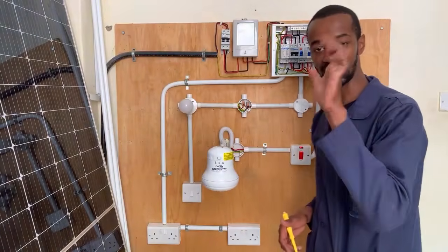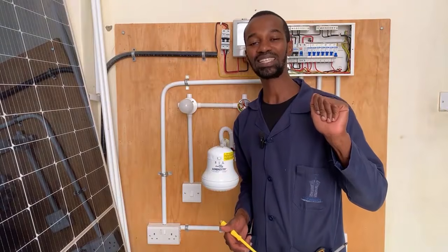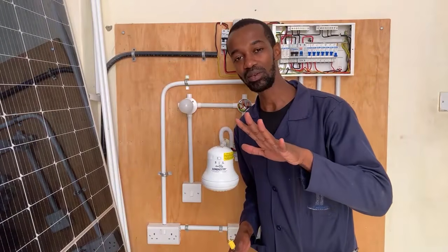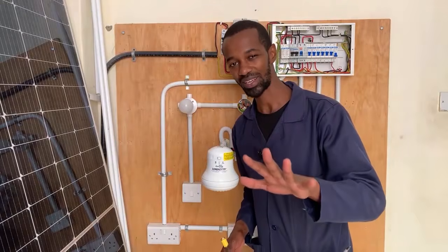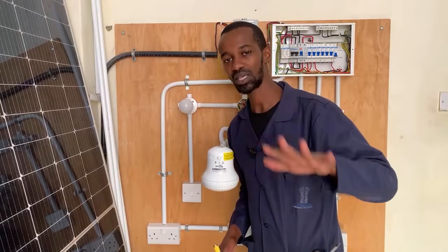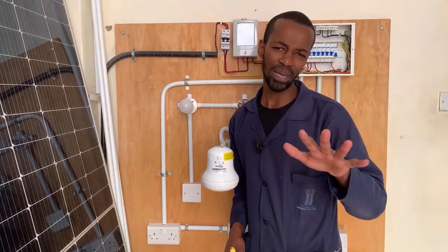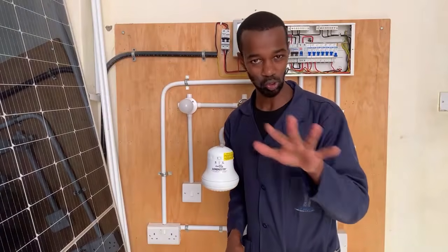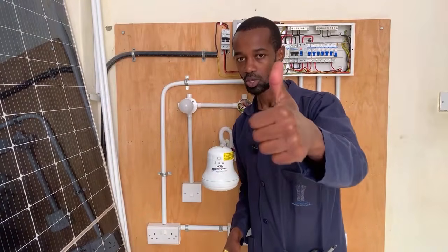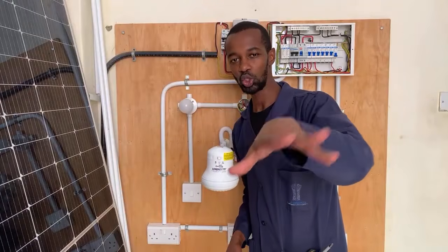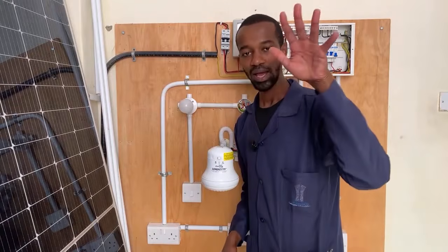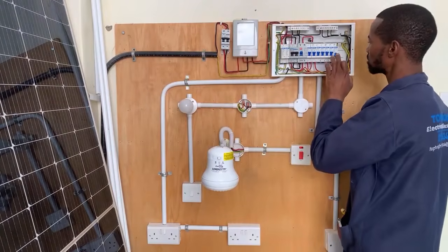One MCB is down. All right. So you will ask your customer, yes, there are no lights. Which one specifically? Maybe they will tell you the security lights are not working. Now, if the entire lights in the home are working apart from the security lights, then it may or may not be an emergency because they are not in total darkness. That means the electrical installation that was done was great. Now, you only have to go and sort out the issue of the security, my top boss. So that MCB is the one that you go and sort out.